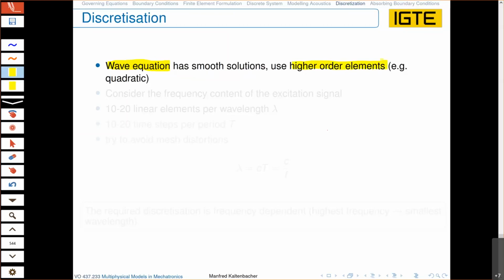So you do not decrease the mesh size, so you do not make the mesh finer and finer, you just leave the mesh as it is, but you increase the order of the basis function, which makes no sense when you have any singularities. If you have a re-entrant corner, for example, in structural mechanics, then you should refine the mesh and not increase the order of the basis function. Anyway, we now have the wave equation, and the wave equation has this special feature.